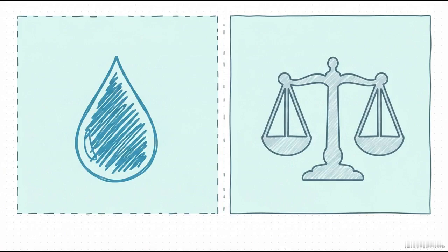When we look at our data, it's pretty wild. 5 out of our 6 meters, that's the differential pressure, turbine, electromagnetic, ultrasonic, and variable area meters, all measure volumetric flow. Just 1 meter on our entire roster, the Coriolis meter, directly measures mass flow. This fundamental difference literally dictates everything about how these devices are engineered and how they're priced.